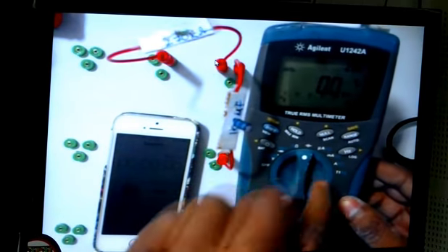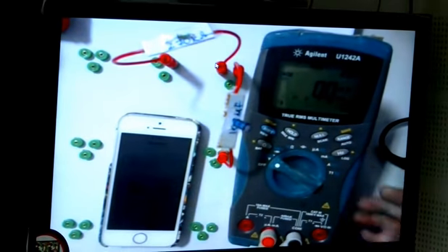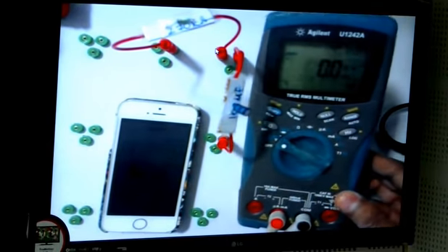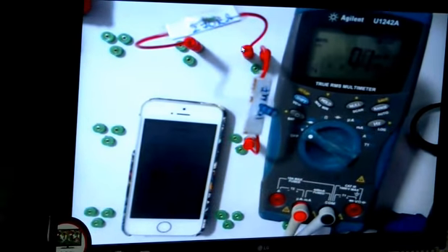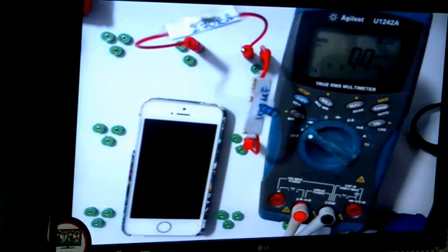So I'll go back to voltmeter measurement. But the problem is the act of measuring the voltage of the capacitor itself will result in the capacitor losing some of its charge. So we'll just quickly measure and then come back.